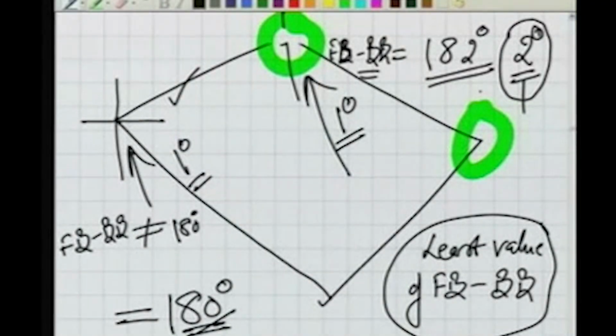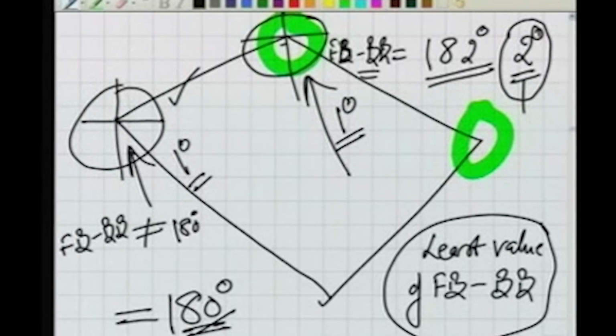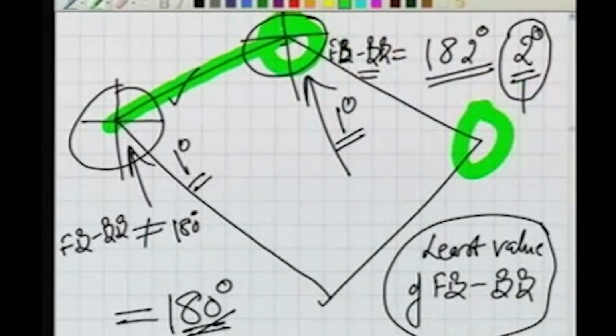And we are making an assumption that we are going to apply the correction equally at this station and this station. So we want to apply the correction equally. So we will take care of the proper sign, and by applying that we are ensuring now, after applying the corrections to the fore bearing and back bearing of this line, now if you find the difference will be 180.